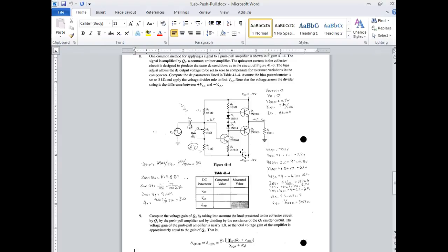So that's most of these amplifiers like this. You have to adjust them. So that's what this guy is right here for. What we would do is we would come over here before we started even working on it. I would put my meter right there, and I would adjust this resistor until this right here measured what? 0 volts. This guy we put 8.